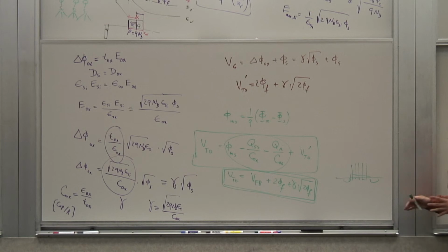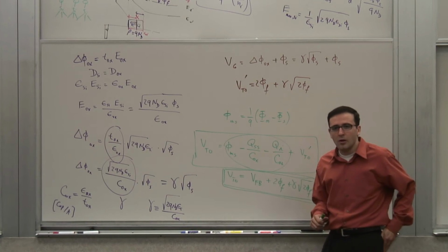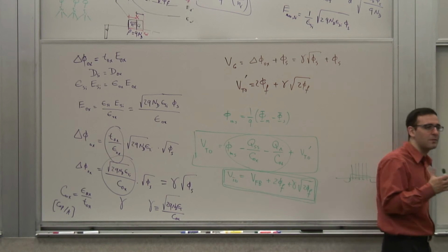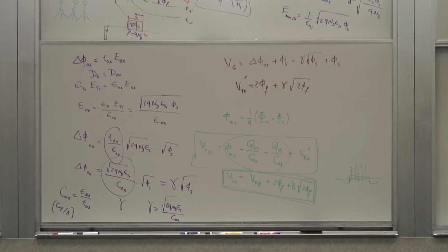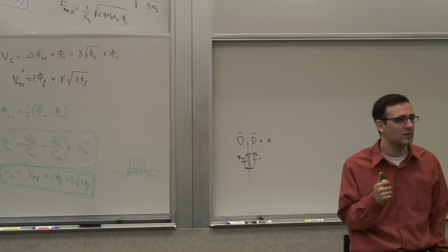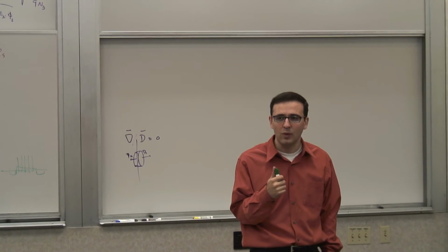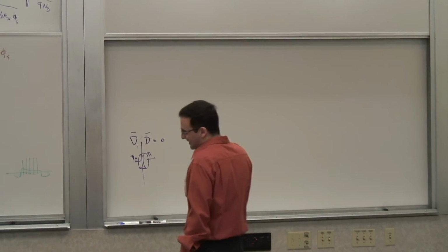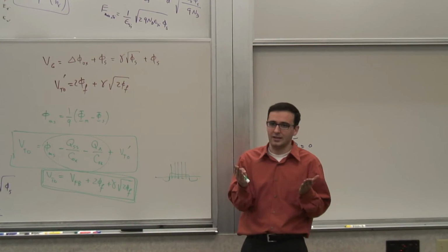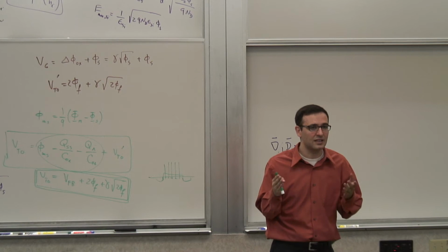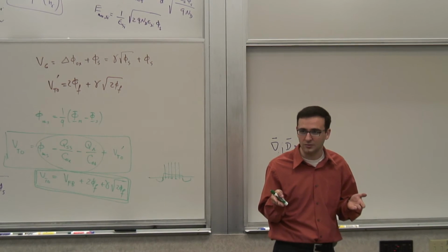Now, I've done all of this to calculate this quantity, VT0, right? But what I really care about, if I want to make a transistor out of this, is the inversion charge density at the surface. So how do I calculate that? Well, I'm going to make an assumption, so keep this in mind. This is a simplifying assumption; it's not technically correct, it's an approximation.